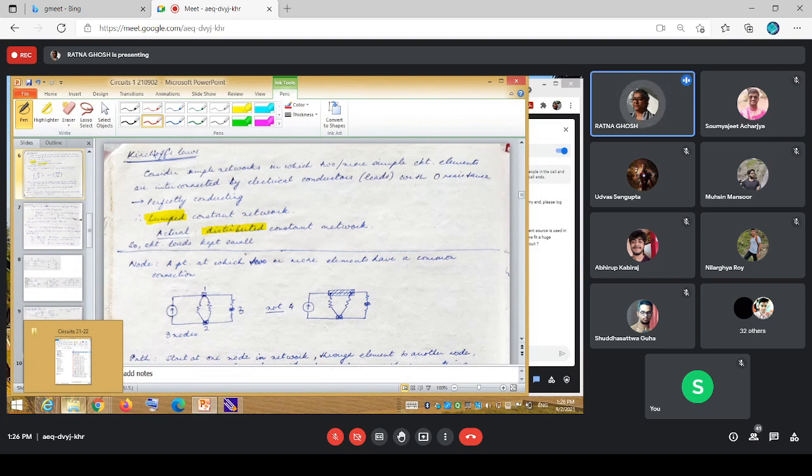But in electrical, the concept has been there right from the beginning of treating systems as perfectly conducting. So the lumpedness is actually courtesy of this approximation, that the system can be considered to be perfectly conducting. As a result, I can lump the total resistance of the system, or the total inductance, or the total capacitance effectively at one point. However large my motor, I can state it to have a single fixed resistance.